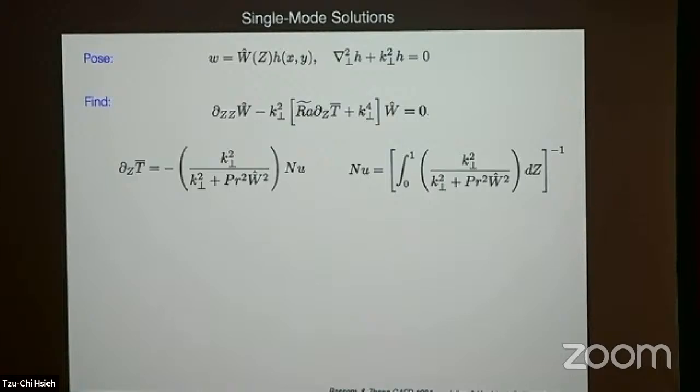There's this non-dimensional number here, the Nusselt number. That's the efficiency of the heat transport. It tells you how much heat is being carried by convection versus conduction, normalized. And we know for the Rayleigh-Bénard case, which I put in yesterday, the non-dimensional temperature drop is -1. So if we integrate that, we can get an expression for the Nusselt number.